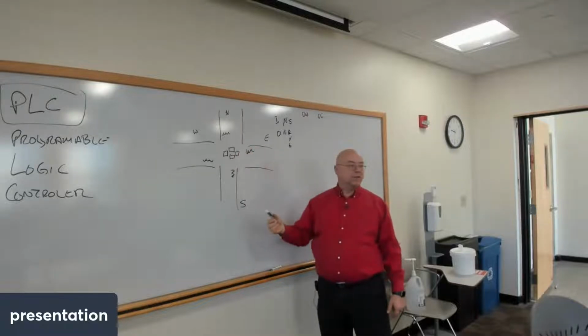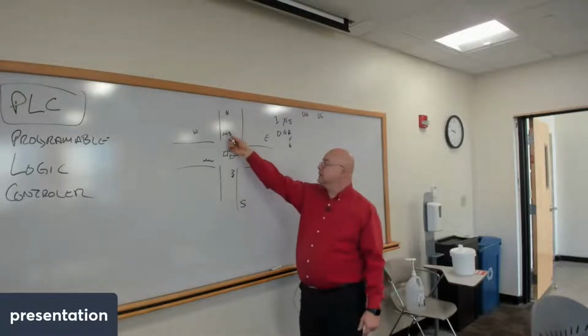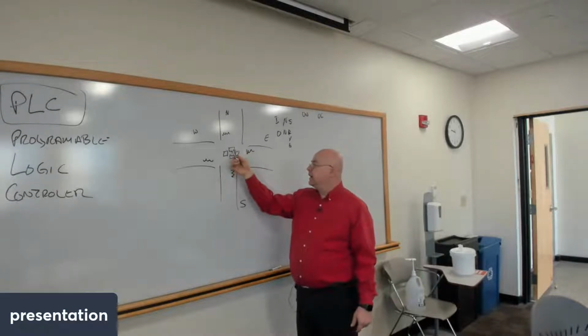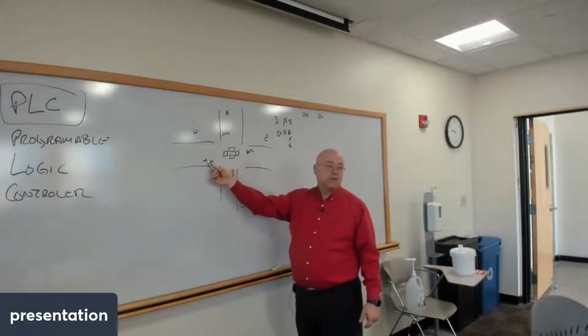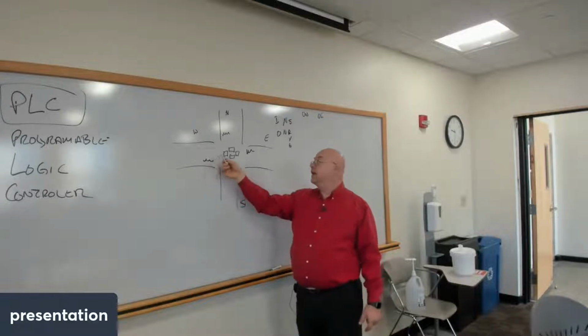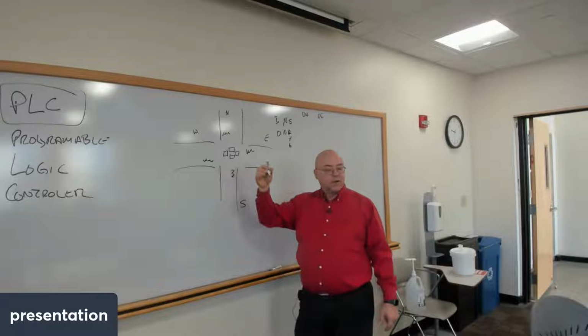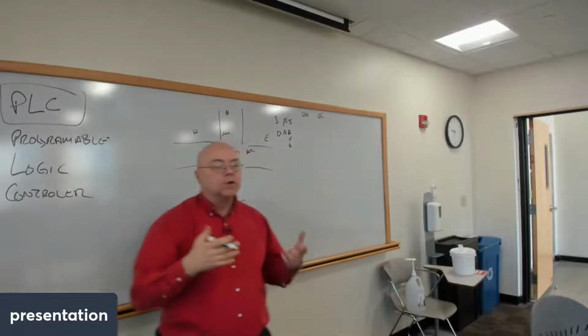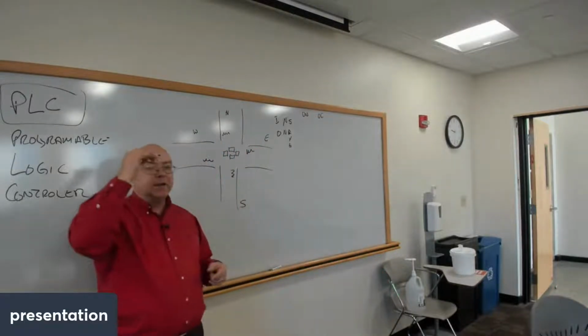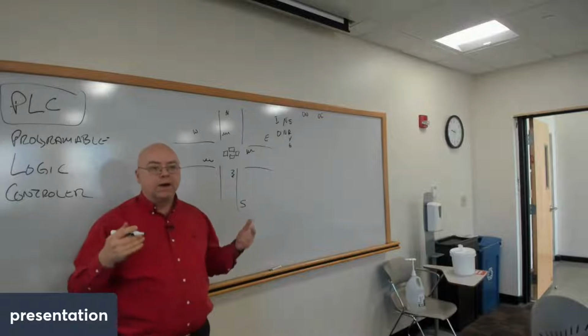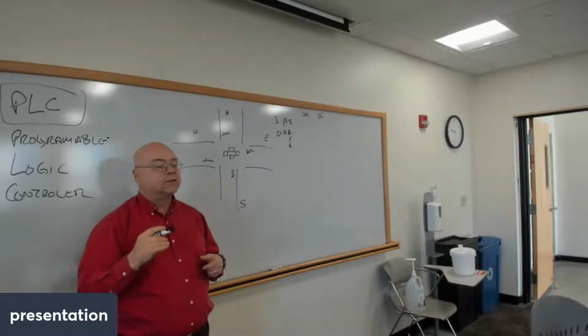Because the car can just drive through. If this sensor is active and this light is green and this sensor is active, you'd have a time delay, and then you'd make this one go yellow to red and this one go green, right? So you set up the logic of what you want it to do in the order that you want it to consider those different factors.